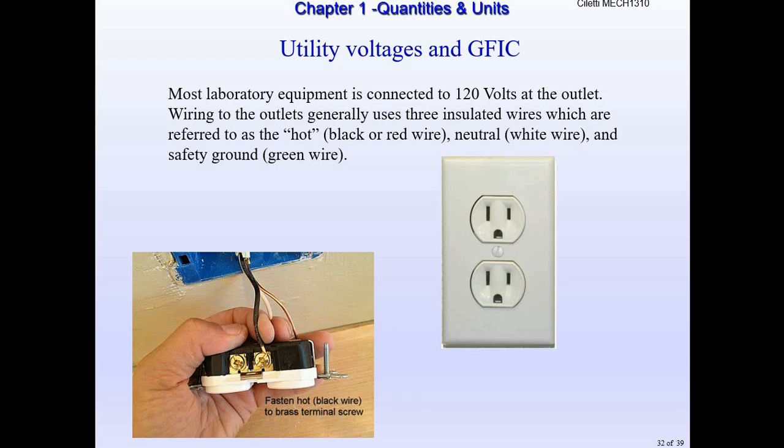Now if you've done wiring in your house, there's a picture of a guy holding an actual circuit from your house. The ground wire when you're doing wiring in your house is not green, it's going to be a solid copper wire, as you can see in the picture there. So the black is the hot, the white's the neutral, and it's common. Always do it that way. But if you buy a light or a fan, it might come with a green wire. Know that that's usually what your ground's going to connect to. So just know those sorts of things.